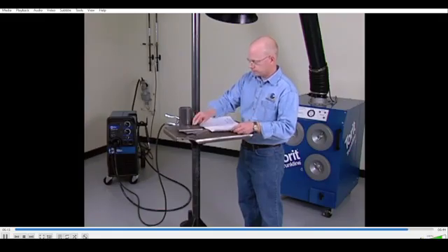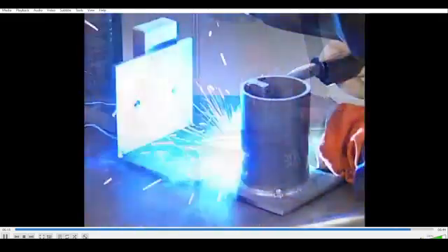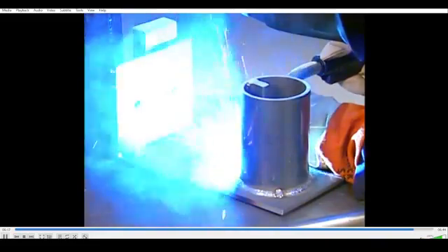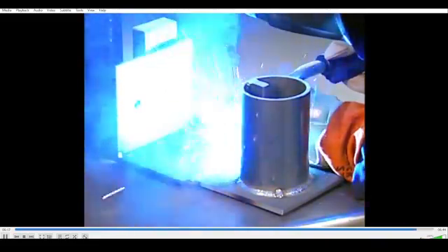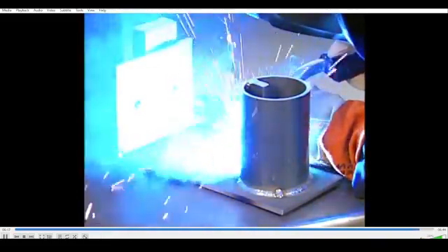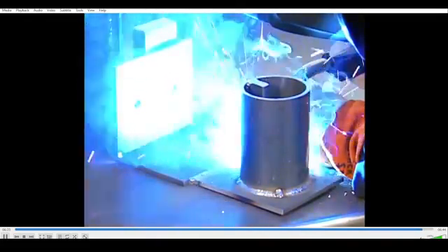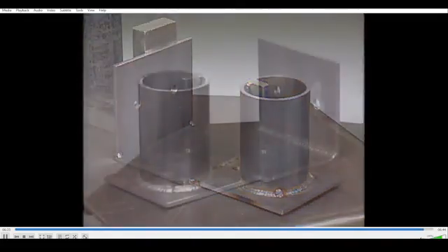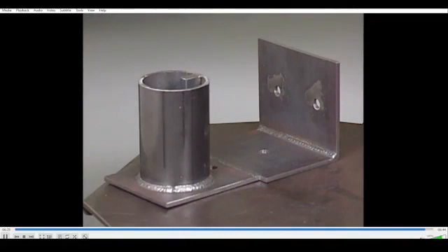However, caution must be taken with evaluating. Welds with good surface appearance are often good quality, but appearance alone will not prove that careful workmanship took place throughout the entire process. All phases of visual inspection discussed must be performed to be confident of required weld quality.